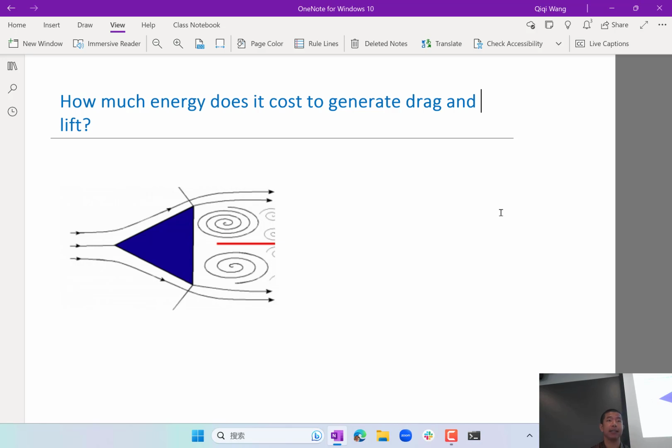That's something we'll look at today, right? So in Unified Fluids, you probably either excelled or suffered from control volume analysis, right? Looking at what is the momentum flux, what is the energy flux, and today we're going to review that and partly explain why it is more efficient to use lift.